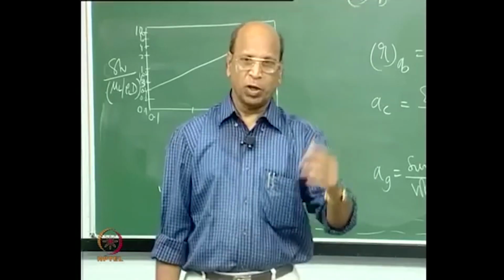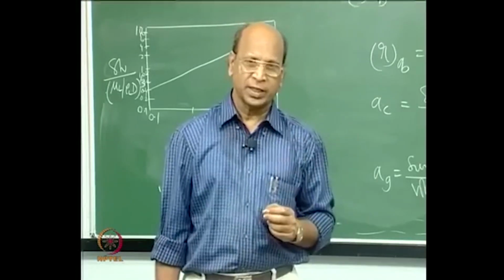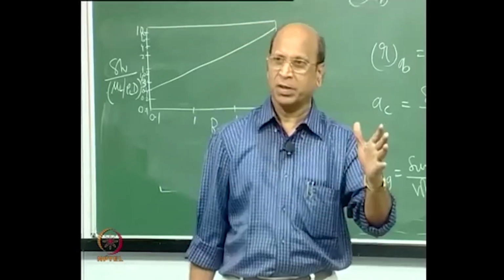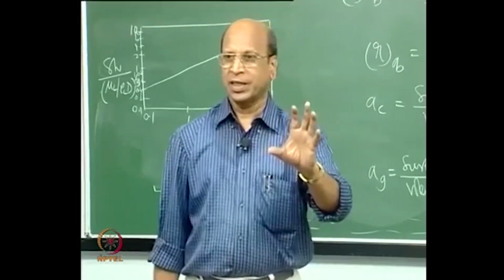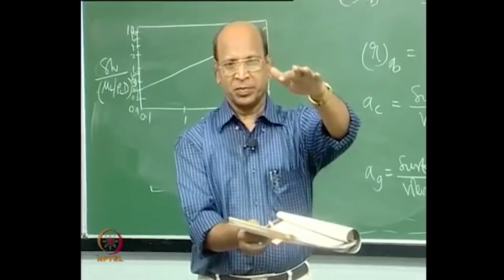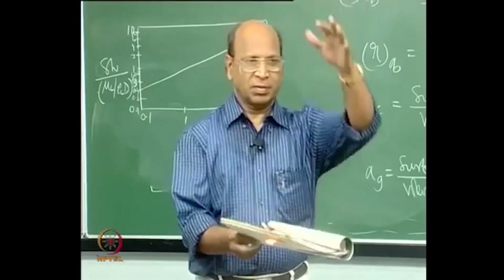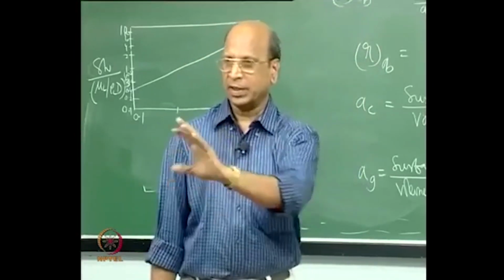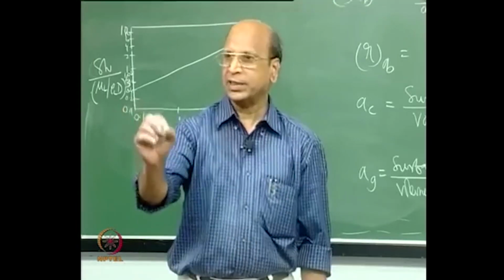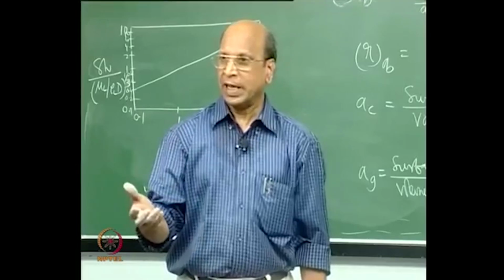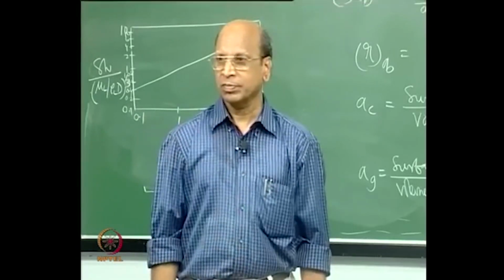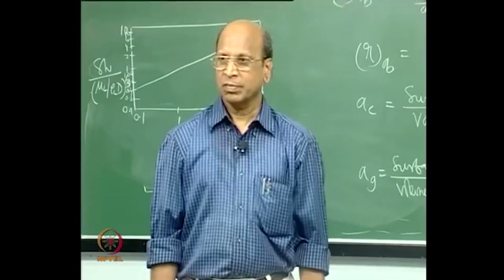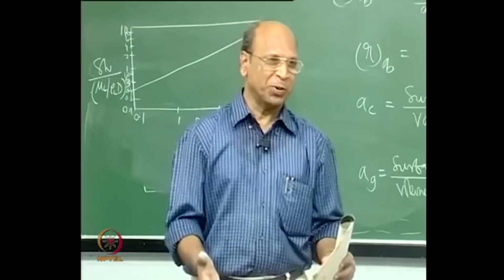That is what someone told centipede has 100 legs, but anyone counted whether centipede has 100 legs? Okay. Similarly, here why I am telling is we believe many things. So, one of the simplest way of finding out bubble size is that you measure the volume of the liquid without introducing the gas, then introduce the gas, because gas has volume, so the volume will increase. So, subtract that increased volume minus this liquid volume, then assume that you have uniform bubbles. Then how do you calculate bubble size now? Spherical bubbles. So, how many number? Whatever number you have, you can get some other value.